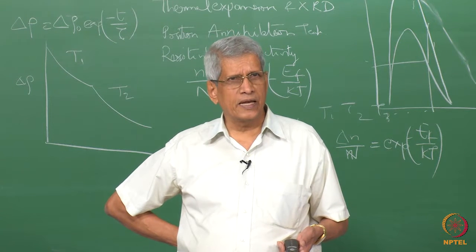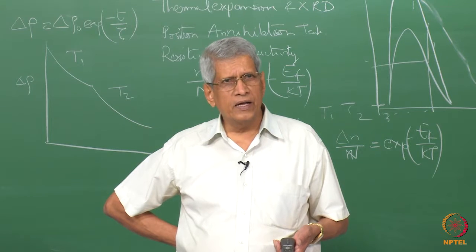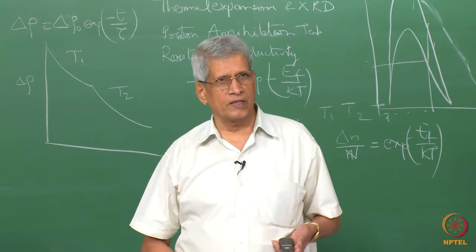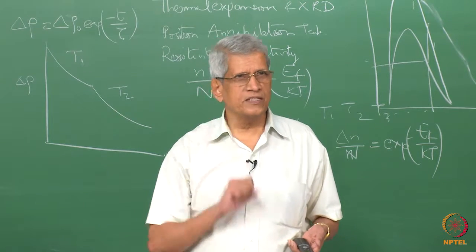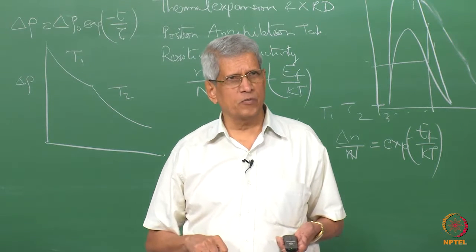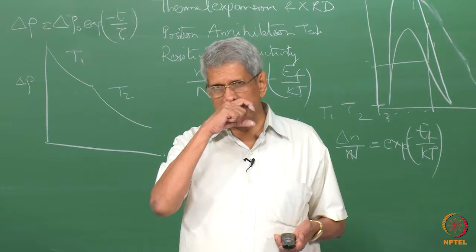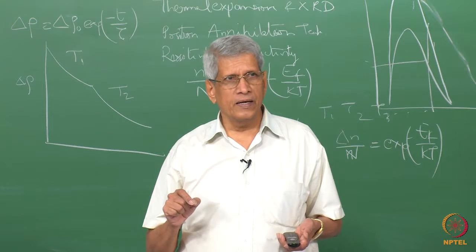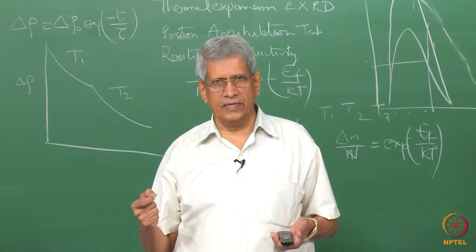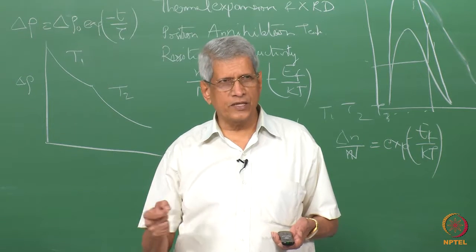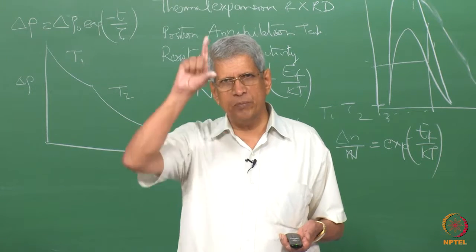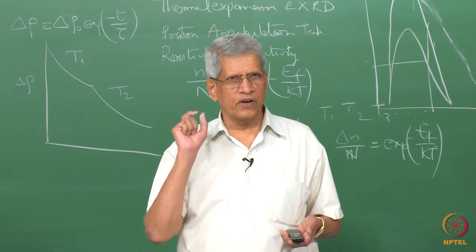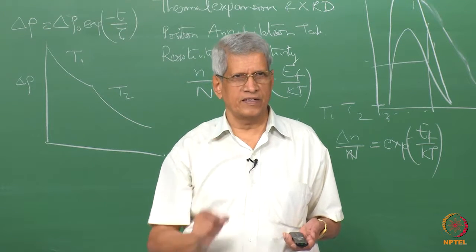The migration energy is related to the rate at which the defects are jumping and finally getting annihilated at some of the sinks present in the sample. So when we change the temperature in this experiment, if the zinc concentration itself changes, then the rate at which the defects are getting annihilated will change. That is why this experiment is performed on a sample which has been initially quenched, and we do annealing at temperatures where the defect concentration or the zinc concentration does not change.